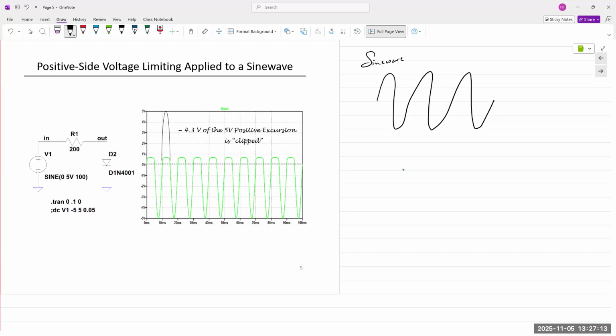If you apply a sine wave input and you're simulating from 0 to 5 volts, that signifies that it goes 0 to 5 in the positive direction, and also 0 to 5 in the negative direction. Hence, you see -5 to +5. So in LTSpice, you simply specify the value of one peak, and because it automatically recognizes a sine wave as going positive and negative, it's going to generate that sine wave.